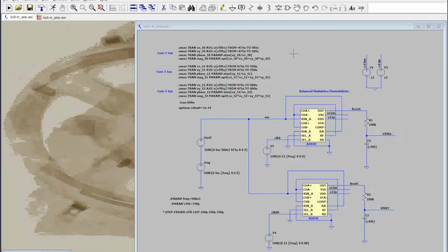So I'm going to first run a baseline with no interfering signal. The signal is in phase with clock 0, so there should ideally be 0 degrees. So the Vx component will be maximum. The V filter X will be maximum, V filter Y will be minimum because you're in phase, and the quadrature component will be close to 0. So let's run this and then document this first.